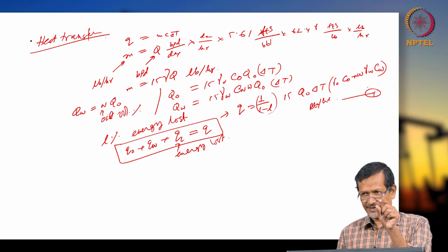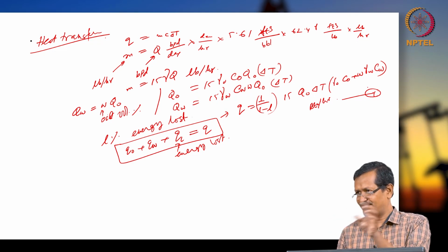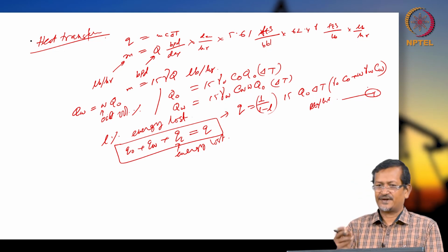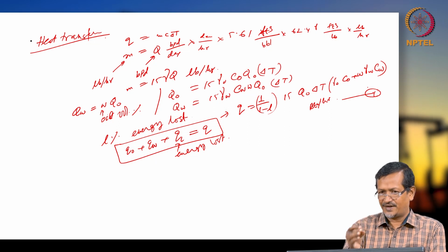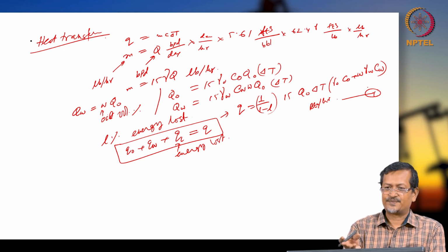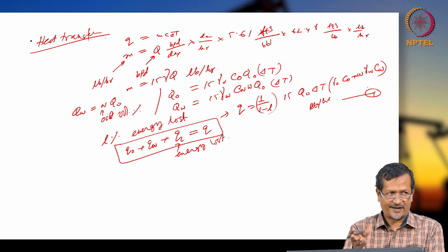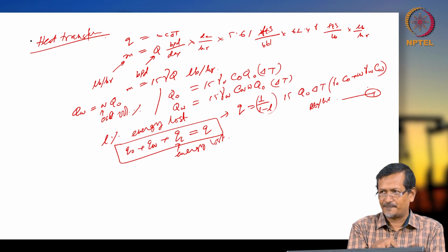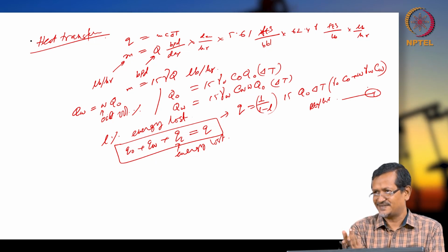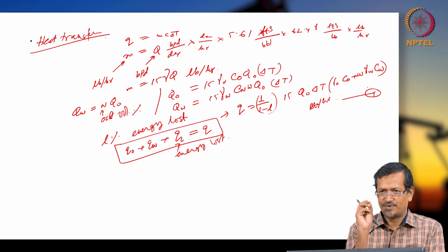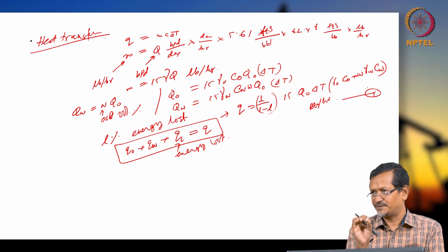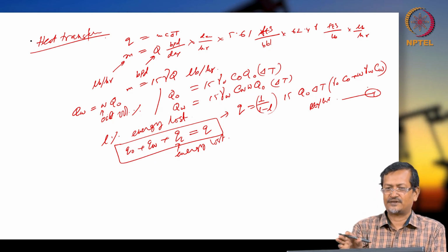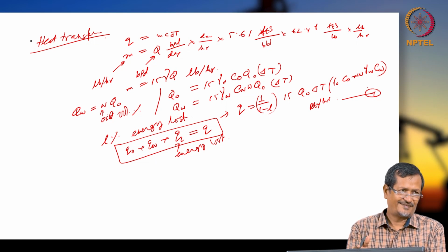Mass, specific heat, and temperature difference give you the heat transfer rate. Now convert units. If I am not giving degrees Fahrenheit directly, and instead give Rankine or centigrade temperature, I can mix it up in your exam. If I give centigrade, you have to convert into Fahrenheit. If you do not convert, it will not match. You must remember those unit conversions, because there are field units, SI units, and many units, and you are playing with units. If you make one mistake anywhere in converting units, then you are gone, you will not get marks.